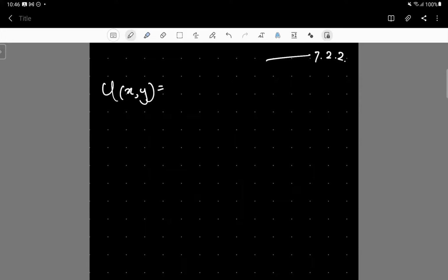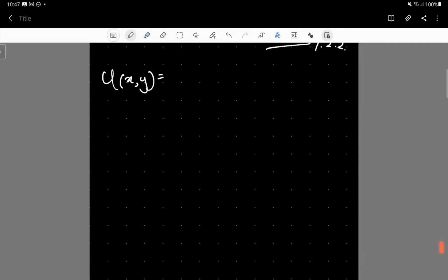So if you do it correctly, you will be able to express the displacement functions u and v in terms of the nodal values, which you find by substituting the nodal coordinates.